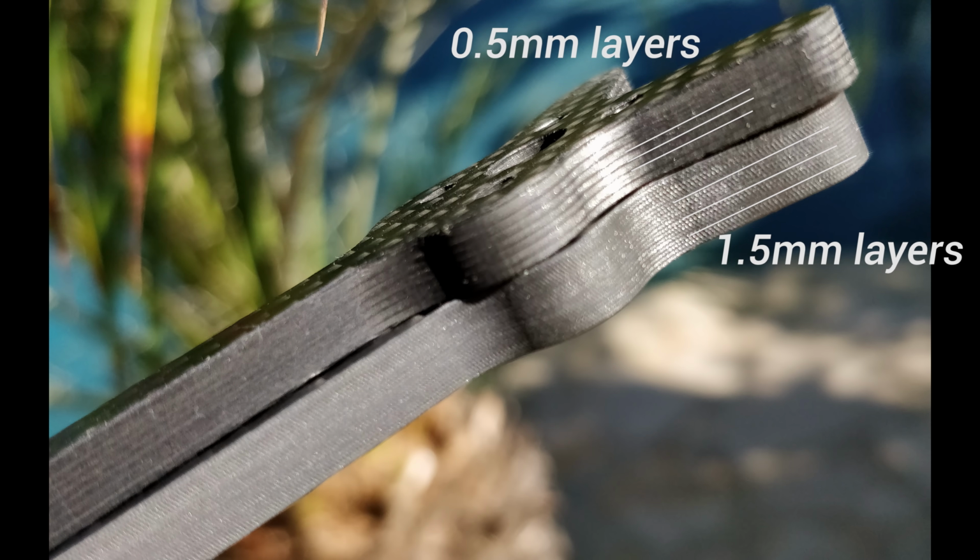But you can have a thick one if it serves a purpose. For example, if you have a zero direction that you want a lot of strength in, that is far out, then you can have a thick one because of that. But if you want to get away with less risk of delamination or something like that, it's better to have a lot of thin layers.